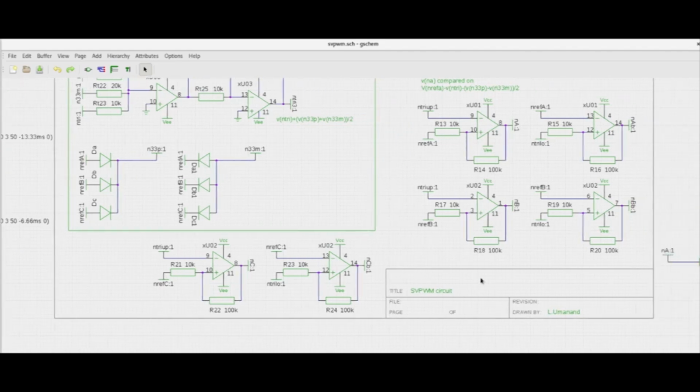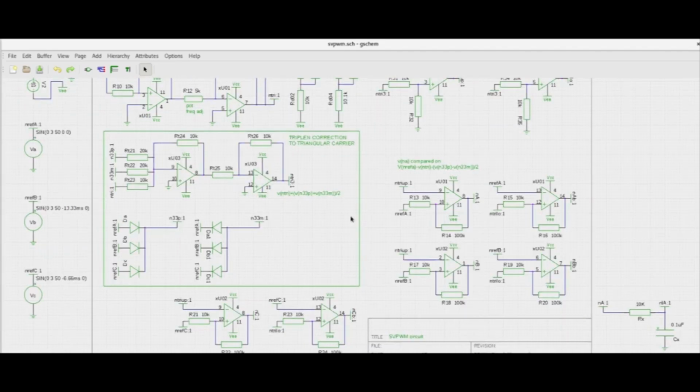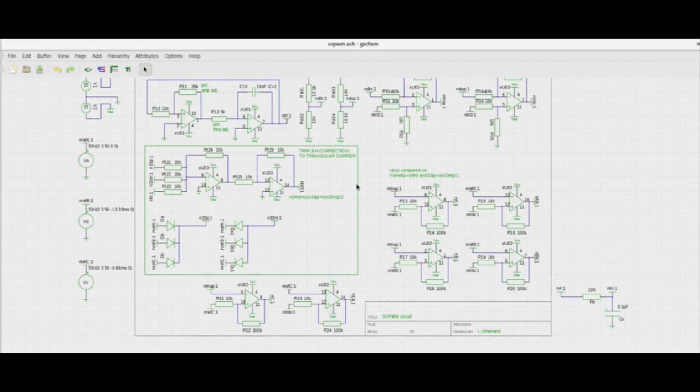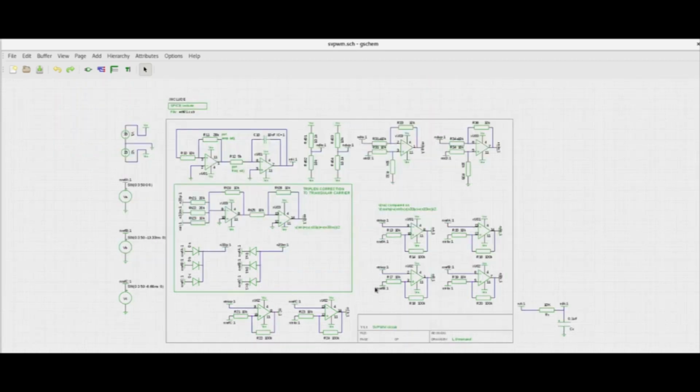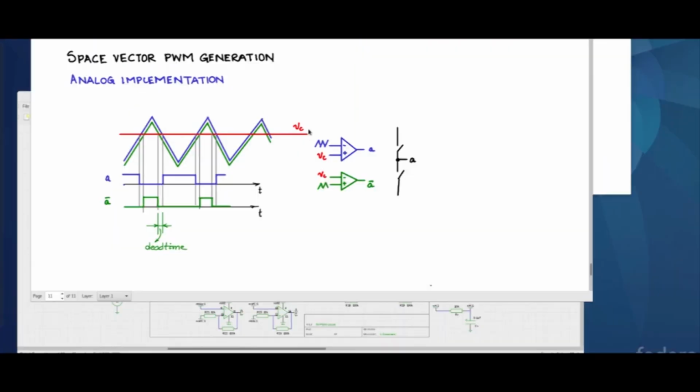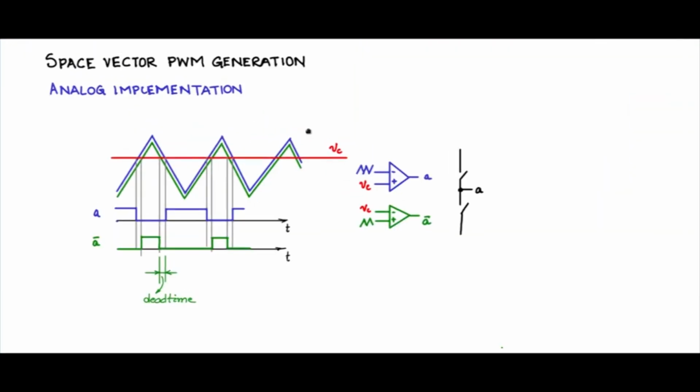Now in a normal PWM, this is fine. Sinusoidal PWM, this is fine. But in a space vector PWM, a third harmonic is injected. Now, why is a third harmonic injected? Consider this timeline and signal. I have this time. Now, I have these extreme limits. This is 100% modulation. These two limits are indicating 100. A sine just touching this line will give you 100% modulation.